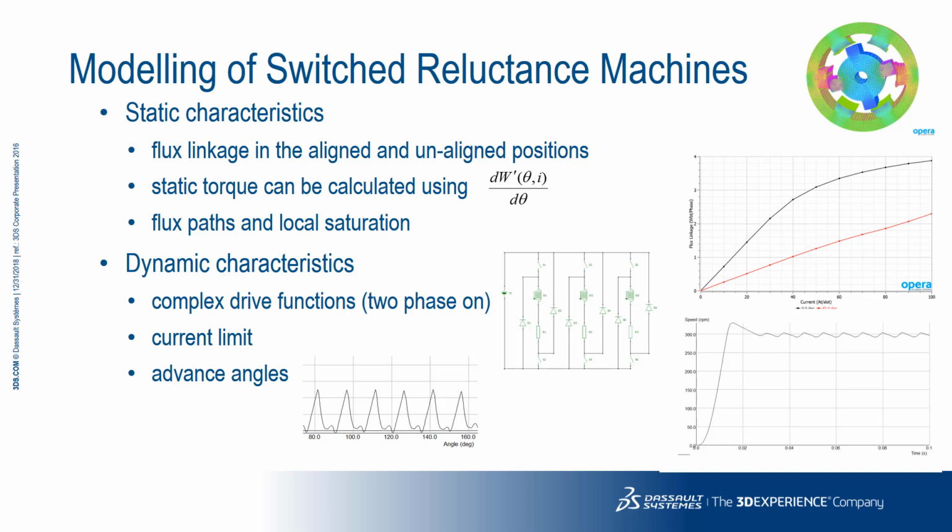Next, the dynamic machine characteristics are important to determine the behavior of the machine with different switching strategies and at different rotor speeds. Based on the conduction time for each phase and the rotor speed, the effect of varying the phase angle on the performance of the machine can be investigated. Since the drive waveforms used for the SRM are not sinusoidal, the model drive circuit needs to be capable of using switching patterns based on the rotor position.